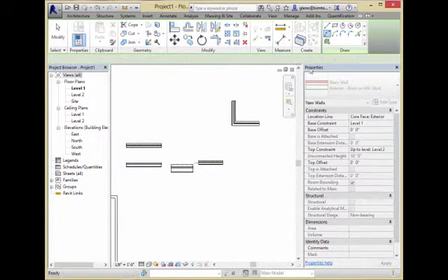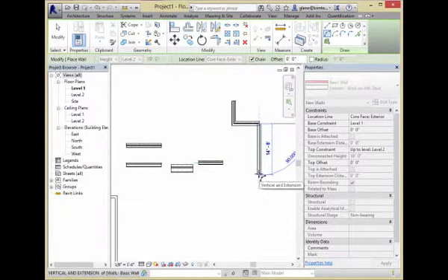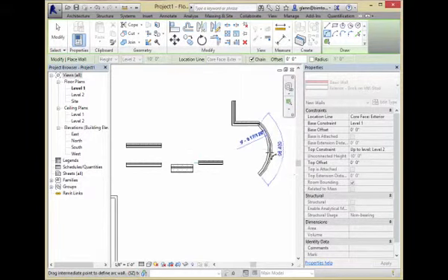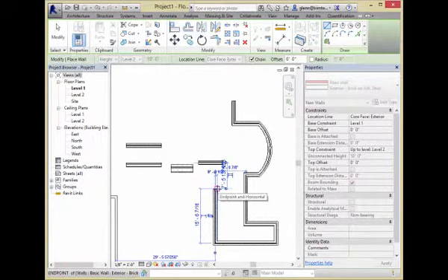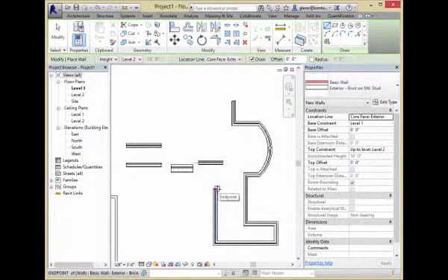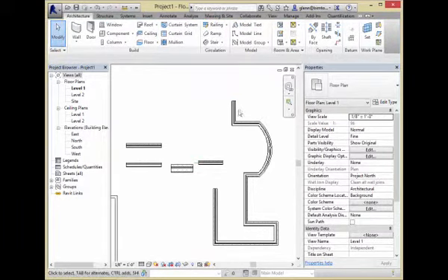Let's put a nice curved wall section in there. You can draw that and arc that out a little bit. Maybe I'll come back here, come over here. But all these now have the same location line. And the groovy thing about them all having the same location line is that later, when I go through and change their properties, they're all going to move relative to that same location line. Let me choose a bunch of walls.